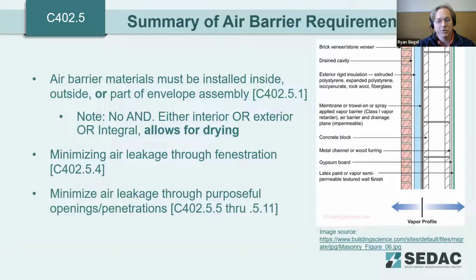Also understanding that for air barriers, you do need to make sure that you're allowing for drying. Most assemblies, even if we do get the details perfect the day of construction, will deteriorate from there. And so water and moisture will enter assemblies. Being able to make sure that that moisture has a way to dry and get out of the assemblies rather than degrade is very important.